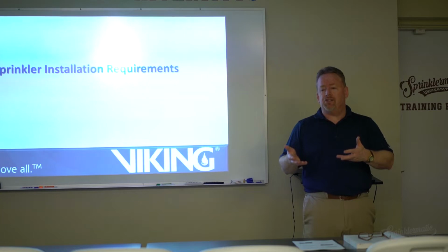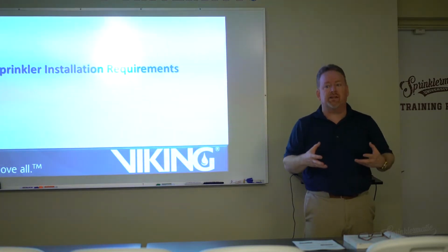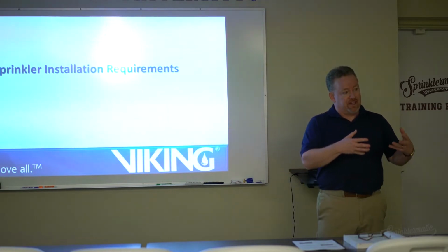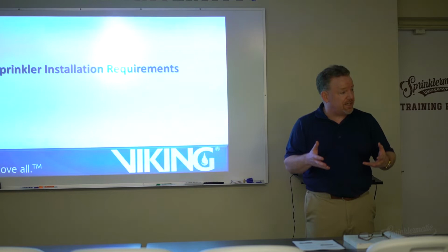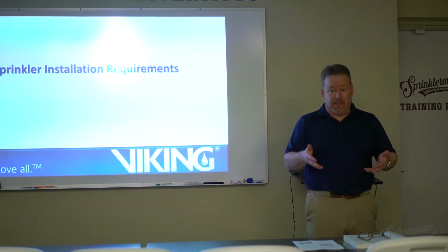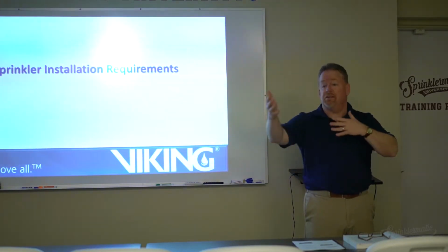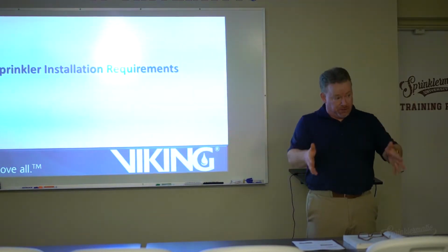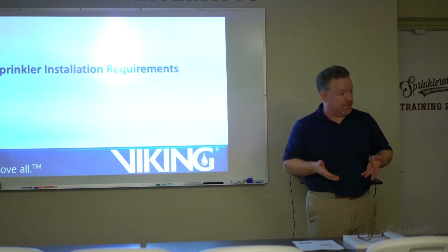We mentioned earlier that if it's a light hazard occupancy, NFPA 13 says you're limited to one type of sprinkler, and that is the quick response sprinkler. There's a quick response extended coverage and things like that, but you're limited to a quick response sprinkler in a light hazard occupancy in a new installation.